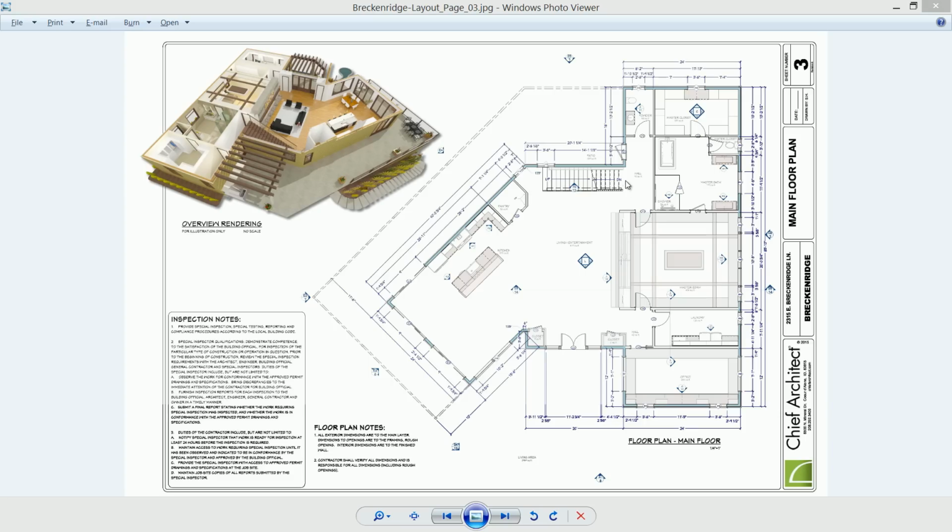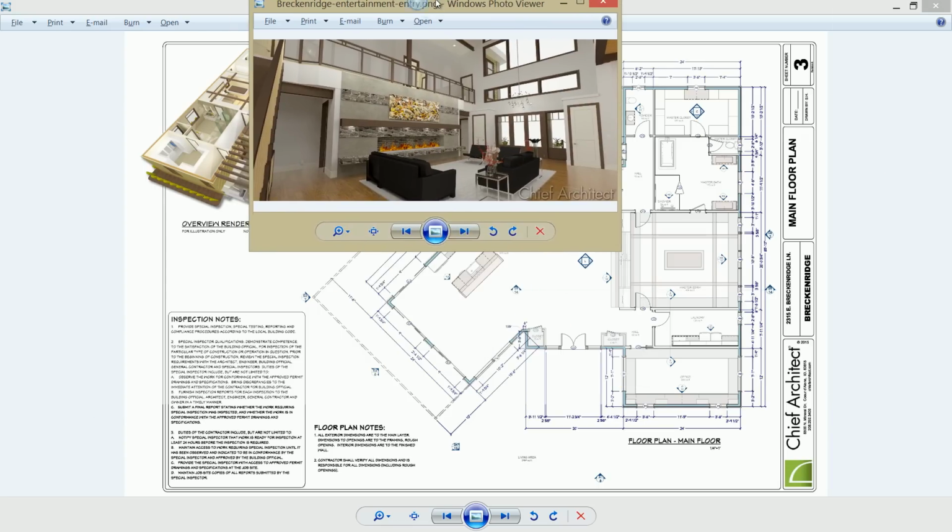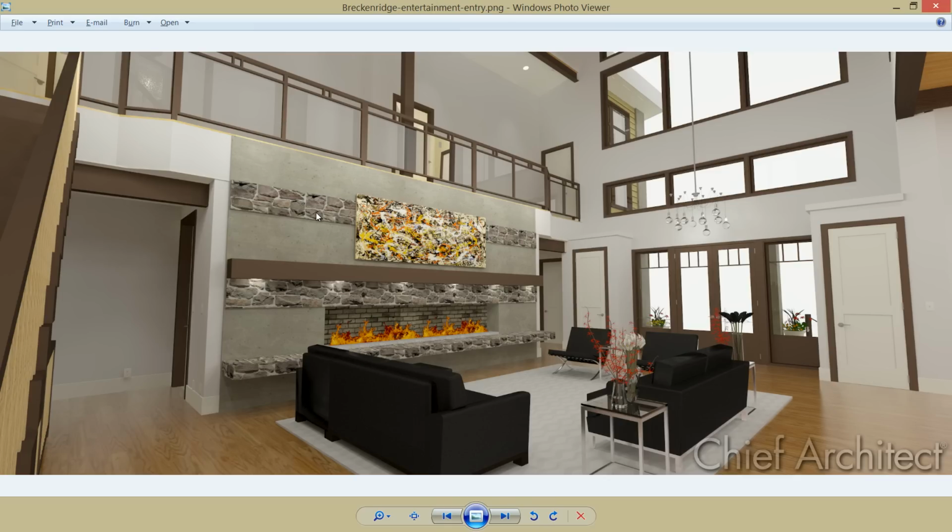So between the hallway, the master bedroom, and the other hallway, I'm going to use a wall. I'm going to then turn it into an invisible wall or a room divider so we can get room definition. And the exact same operation I'm going to do for the kitchen because that is going to have a shed ceiling. And just to give you an idea what the master bedroom fireplace looks like, it's a double-sided fireplace, but I have a privacy panel between the two viewports so that is not actually a see-through fireplace.